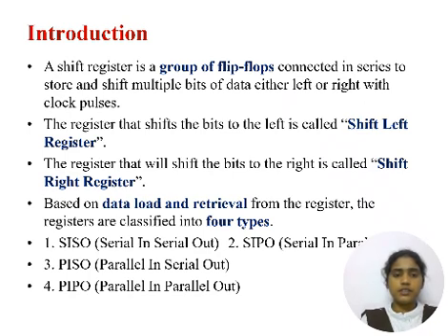Introduction. A shift register is a group of flip-flops connected in series to store and shift multiple bits of data either left or right with clock pulse. The register that shifts the bits to the left is called the shift left register. The register that shifts the bits to the right is called the shift right register.